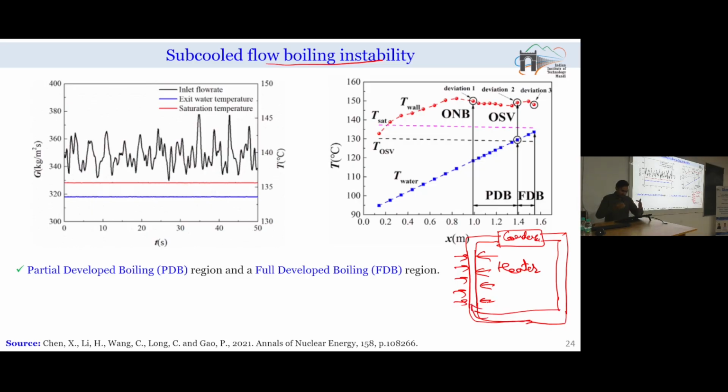Of course, in the actual arrangement, above the heater section we need to keep a large-height riser section so that we can actually achieve the necessary head. So, now when we heat the working fluid in this heater, what will happen? This working fluid, because of the decrease in its density, will rise in the upward direction, and from here it will fall in the downward direction.